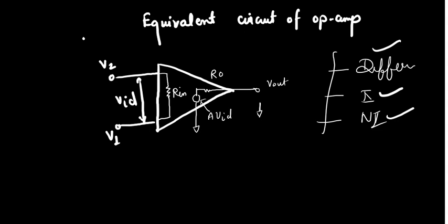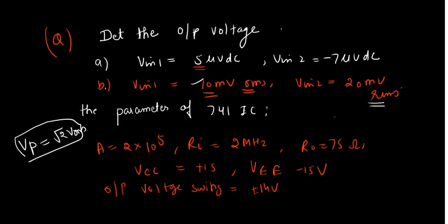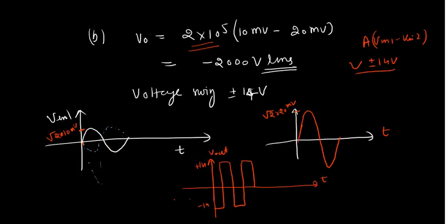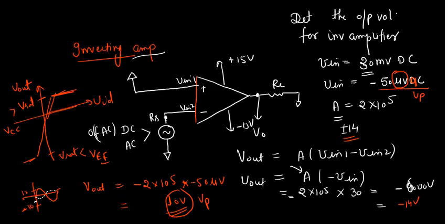And according to application, we choose these type of configurations. If you want to invert the signal as well as amplify, we would choose simply inverting amplifier, right? If you don't want to invert, we just want an amplification, we would use non-inverting amplifier. So we have seen if we use these 3 configuration along with the open loop type of arrangement, there will be few drawbacks. Drawbacks is a very small signal goes to clip, it clips, right? Go to saturation. So we cannot amplify very small signals, and also we have seen the bandwidth is quite small. So it is impractical in a way.